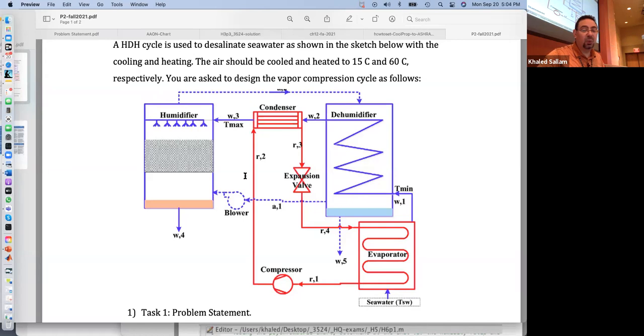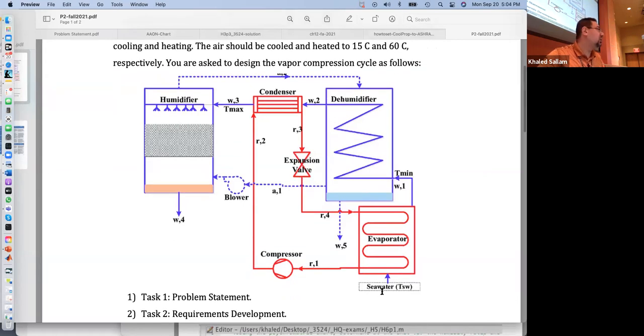Okay, and what is this water? This water is seawater, the salty water, water with salt content in it. So when the water evaporates here in the air, what evaporates? The salt will not evaporate. Only pure water evaporates. So pure water evaporates and the air carries it, and then the air drops it in this place. So the brine or the seawater gets sprayed and very concentrated brine comes out, but the clean water is separated over here. So W5 and W4 equal W1.